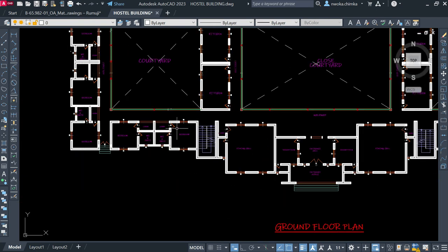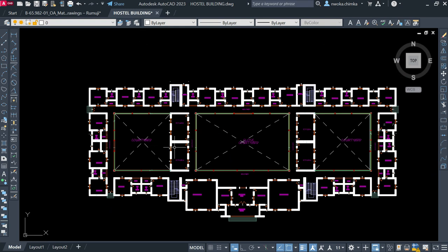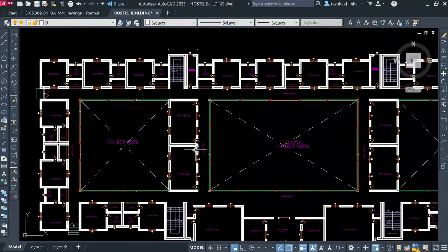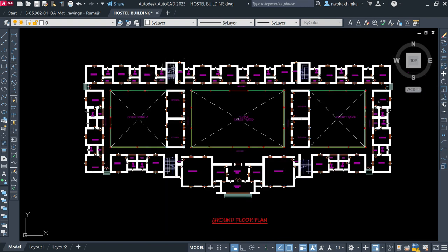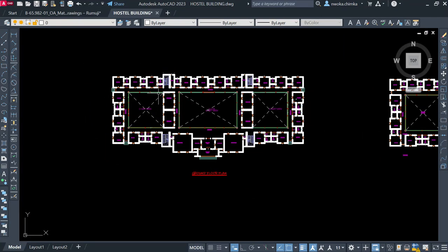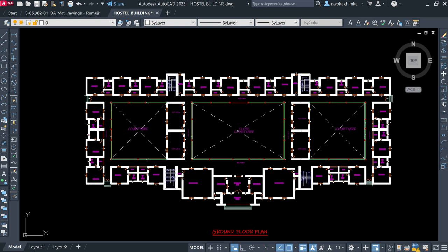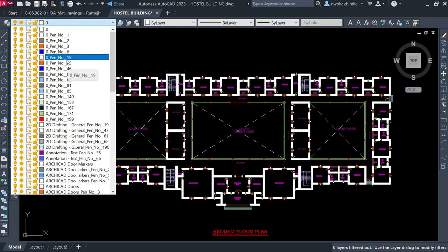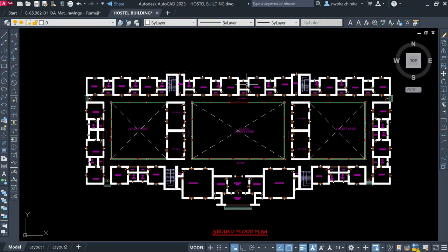Now, the software which we will be using for the structural design is Prota Structure software. As we all know, it is one of the most powerful softwares which we have today in the building structural design industry, and we will be using Prota Structure to perform the structural design. So for you to export your building plan into Prota Structure, you have to create two layers, one for grid and one for columns. Only by creating those two layers, grid line and column, will the software Prota Structure be able to recognize that this is a building plan.